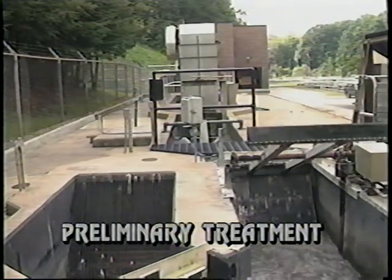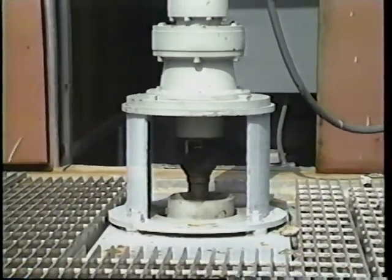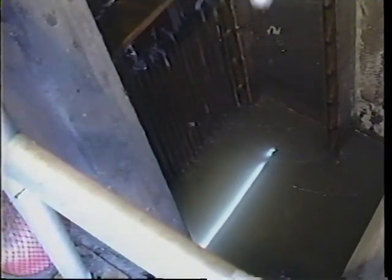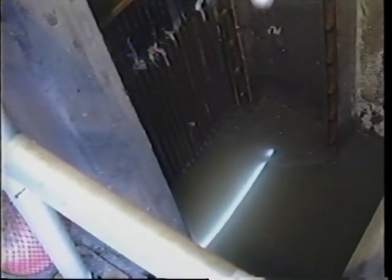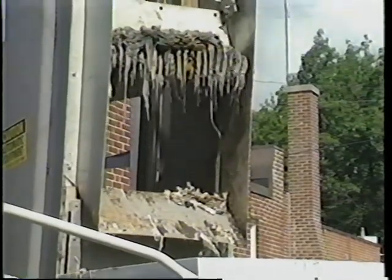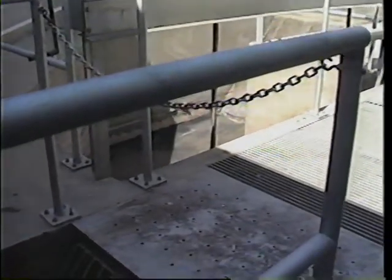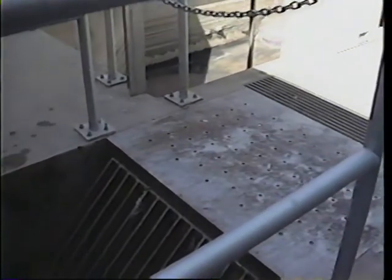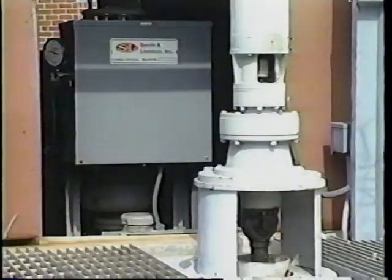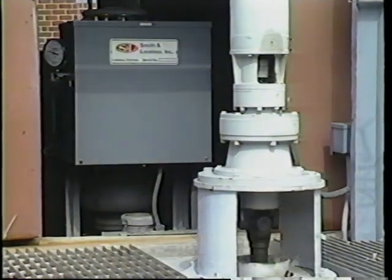First, the wastewater usually passes through a bar screen or comminutor for removal or shredding of larger debris. The bar screen performs a simple but important function. The removal of large debris at this point protects equipment and reduces the possibility of interference with in-plant flows. A trash rack may also be used in conjunction with a bar screen or comminutor for removal of very large debris. A comminutor or barminutor may be used in place of or in conjunction with a bar screen.